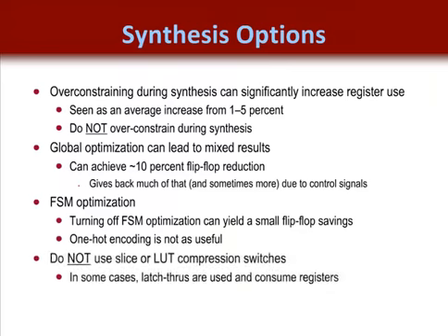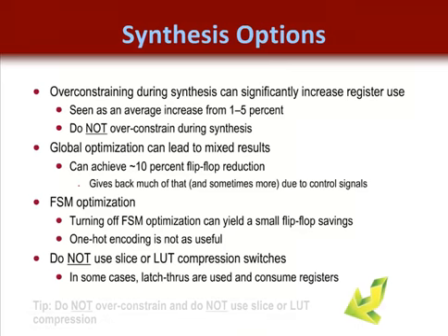Finally, don't use slice or LUT compression switches. While this does not consume too many extra flip-flops, in some cases latch-throughs were used, and this wastes registers. Recall that the slice does not allow you to separate the flip-flop from the LUT, so in the case of a latch-through, the LUT is used, but the flip-flop is wasted.